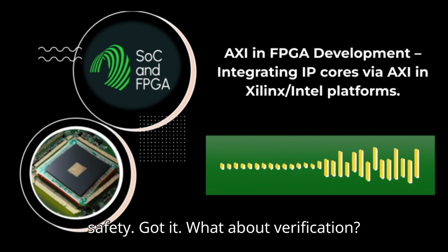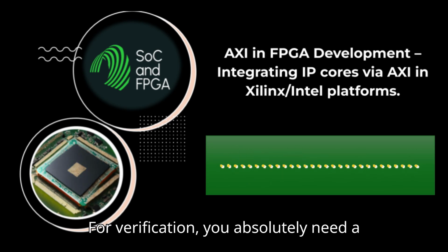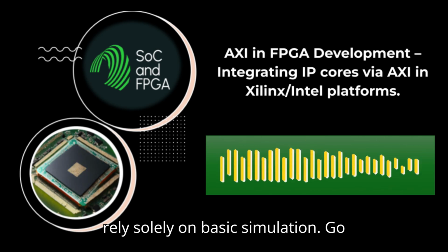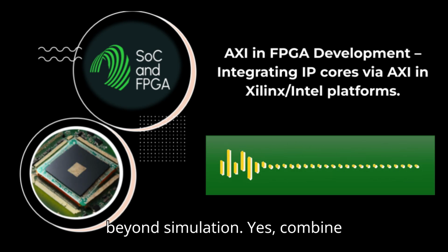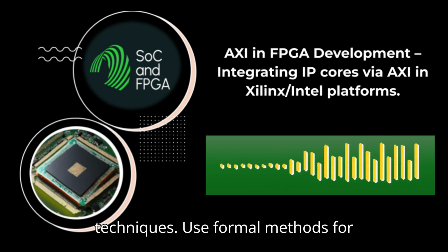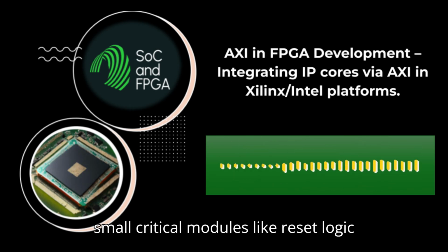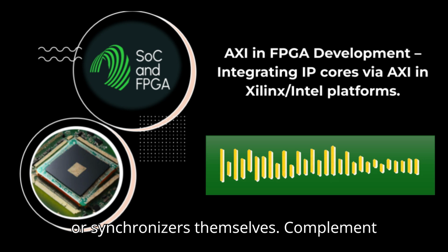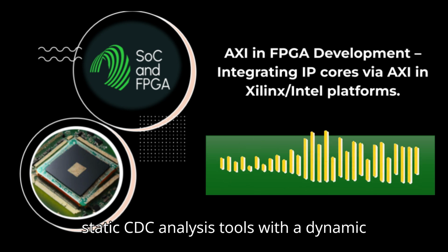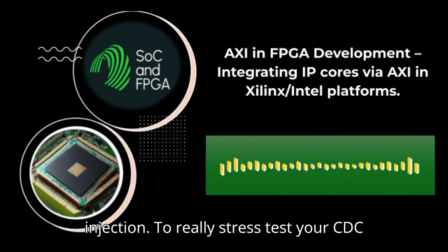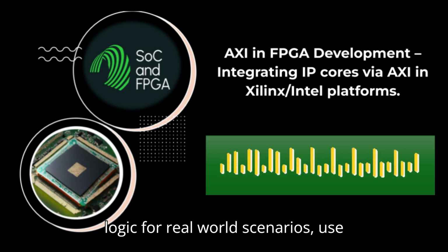Got it. What about verification? For verification, you absolutely need a comprehensive, coverage-driven flow. Don't rely solely on basic simulation. Go beyond simulation. Yes. Combine techniques. Use formal methods for small critical modules like reset logic or synchronizers themselves. Complement static CDC analysis tools with a dynamic simulation using metastability injection to really stress test your CDC logic for real-world scenarios. Use formal and MSI.